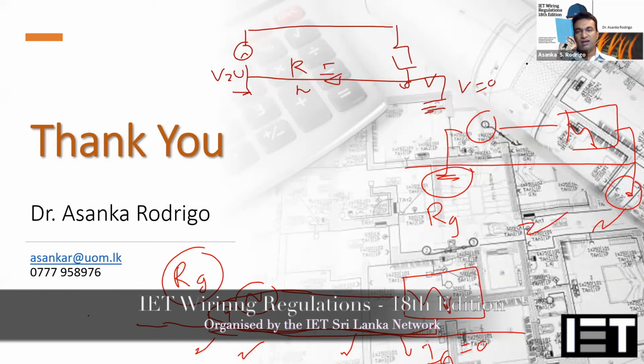Actually, I focused on the rated diversification factor, like a case or something like that. Right. When you look at the diversity factor and the utilization factor, what the standard says is it's up to the designer. There is no guideline given, because it depends on that particular installation. It's the designer's requirement to evaluate the operating pattern, the type of operation, and how the user is going to operate this equipment, and decide the proper diversity factor and utilization factor.